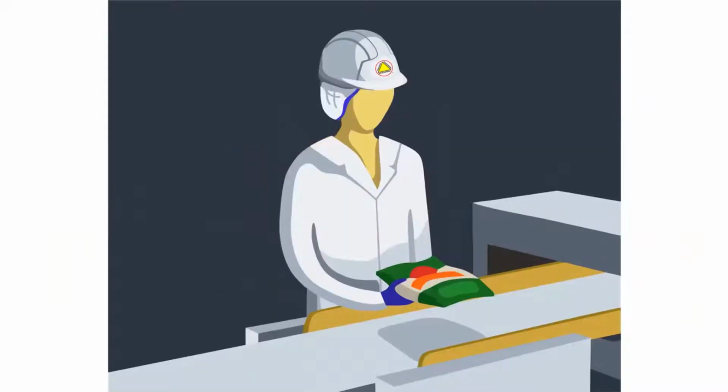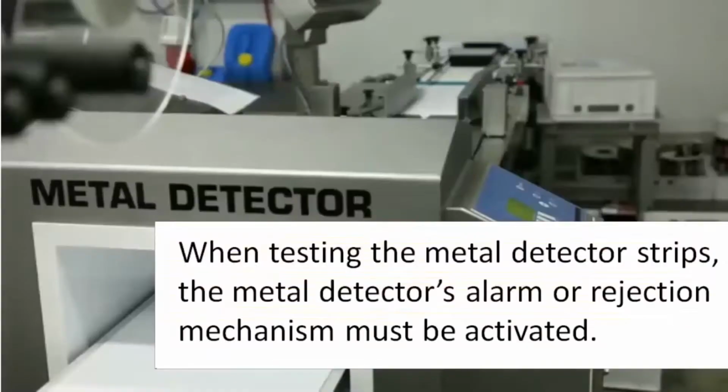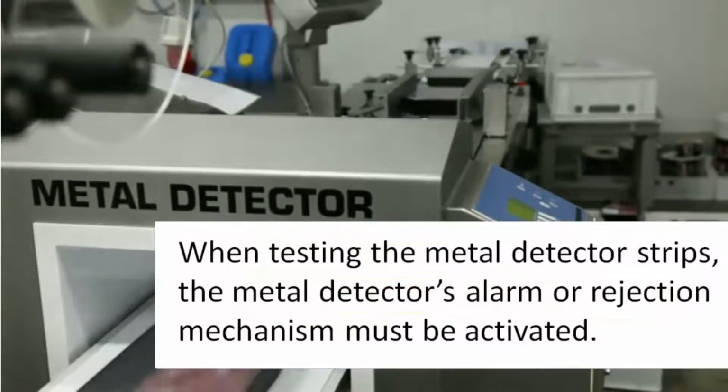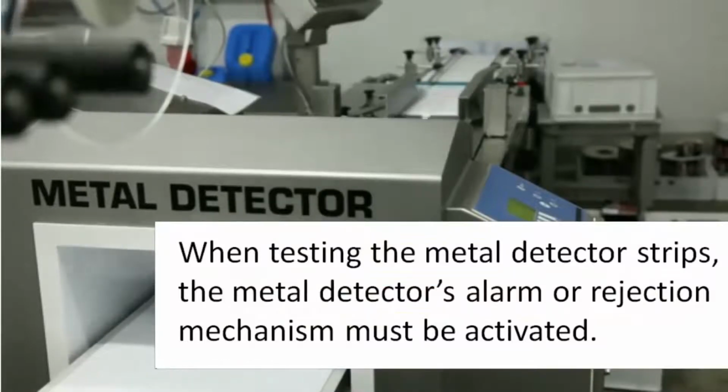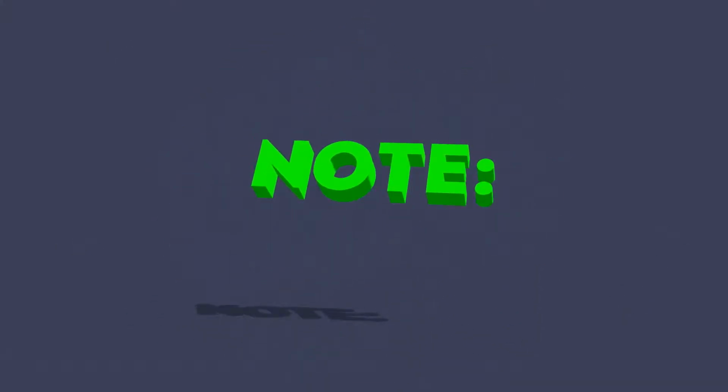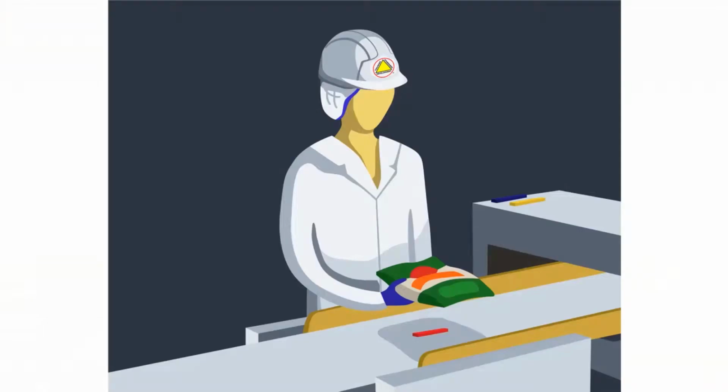These next images demonstrate a way to perform the monitoring procedure. All metal detector strips must be tested through the metal detector individually. When testing the metal detector strips, the metal detector's alarm or rejection mechanism must be activated. Note: the test strips must be located approximately at the geometric center of the metal detector.